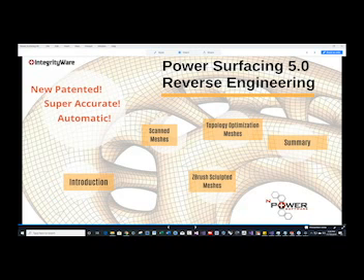And typically while we're doing that, we will give them some of the rules of thumb we use for design. For example, use as few control points as possible, and then as you need detail, you add more. So you start very low and you add more. You saw most of the models here did not have a whole bunch of quads in them. The power surfacing ones were fairly simple, and then we would just add detail if we need it.